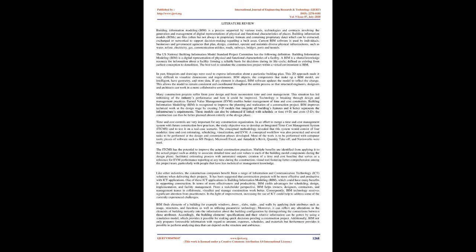As the majority of the building construction was completed at the time of the project, we collected the actual start and finish dates of construction of different components and parts of the building. We created a CSV Excel file with the time schedule of the entire construction process, including start and finish dates of each process. The file was then added to Navisworks Manage.